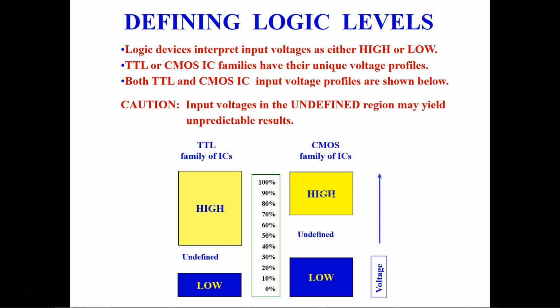They use a symmetrical pair of P-type and N-type MOSFETs, and it has high noise immunity and low static power consumption. So both TTL and CMOS circuits have four electrical characteristics. Right now we are not going to get into detail of those characteristics. We will just focus on the voltage profile.